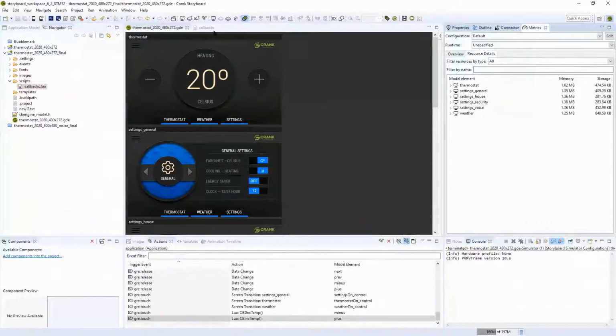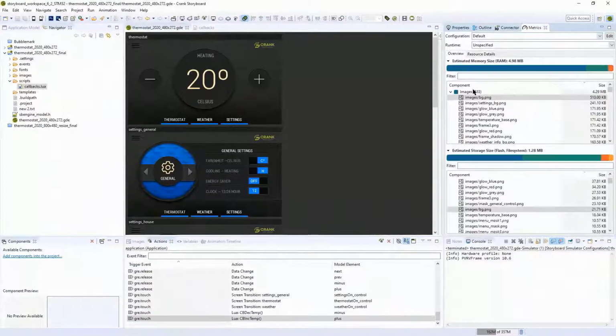So as part of the export, what we can do is look to optimize the way that we're deploying these. If I switch back to the overview here, you see, if we keep this as standard, we're going to be taking these compressed models and files and expanding them at runtime. So we're going to be taking up a relatively large amount of memory. This doesn't include the frame buffer size, so the number of pixels on the screen times the color depth. That will be added on top of this as well.